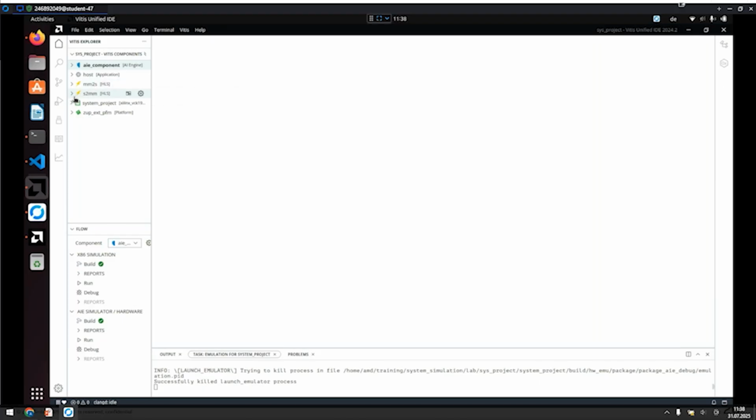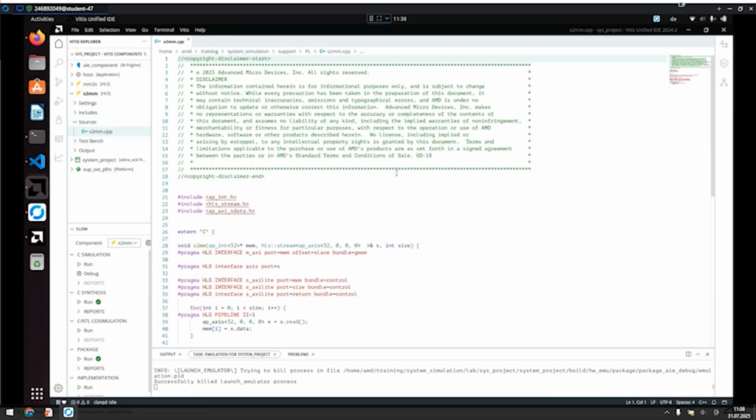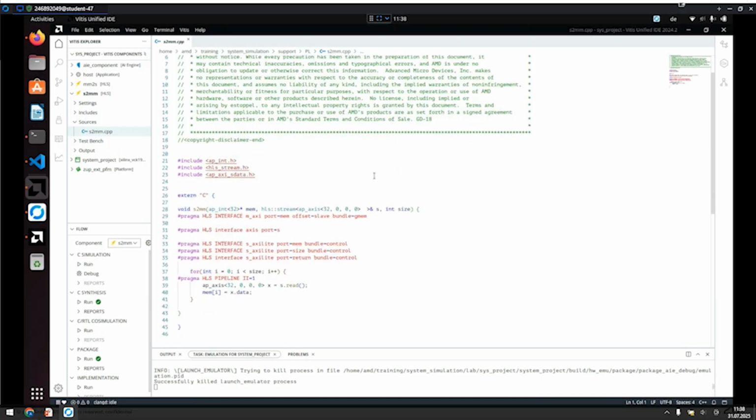And it has HLS kernels. If I'm using HLS to create my HDL code, that's also C code. So you will find the C operations. You will be able to address the different input-output interfaces from your function signature, and you will finally see how this whole thing operates internally. In this case, it's reading from an addressable field, streaming out into a stream. There's another kernel that's doing the other job, like taking in a stream and mapping it out to a memory mapped interface.